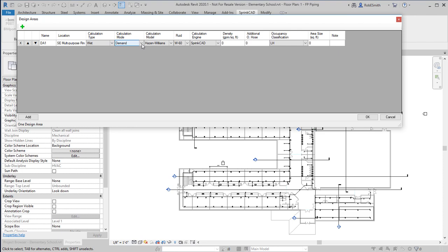You can also choose between demand and supply calculations. Without going very deep into the subject, a demand calculation is one where you begin with the operating fire sprinklers. Or in the case of a standpipe calculation, you begin at the most demanding standpipe outlet where pressure and flow are specified by code. And you establish the required pressure and flow at that most remote outlet, be it sprinkler or standpipe outlet or fire hydrant in the case of calculations for fire flow in a building site.